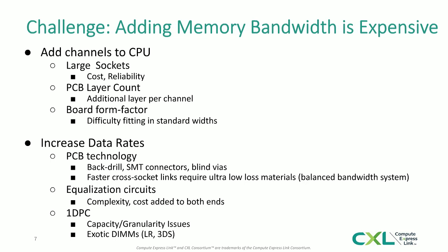These sockets are not only expensive to make, the contact reliability also becomes quite hard to solve. The second issue with adding channels is that you have to route those channels, and that needs additional PCB layers, which is also a cost adder. The third thing is that to accommodate all these DIMMs that you're adding because of the channel add, you have to figure out how many DIMMs you can place while still being able to fit in a standard rack width.